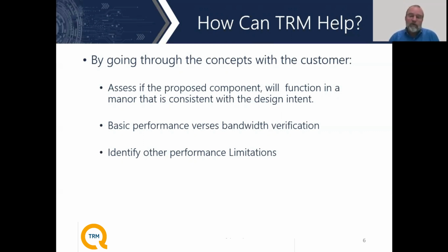The other thing that we talk about is just basic performance of a lot of our passive components. Again, system engineers aren't always fully in the knowledge as far as performance trade-offs, specifically about bandwidth versus things like insertion loss or VSWR. There are definite trade-offs that need to be made within those bandwidth discussions, and also other performance limitations. Like I said, I certainly don't expect the system engineer to be fully up to speed on the subtle trade-offs that are made within our components, and having that discussion makes sure that what they're asking for really can be built.